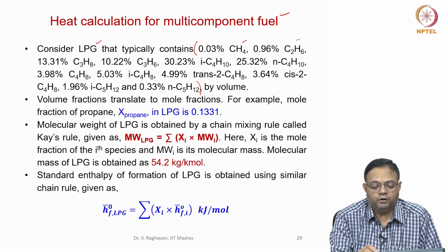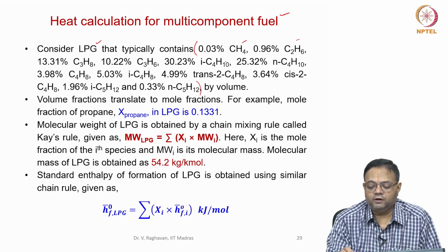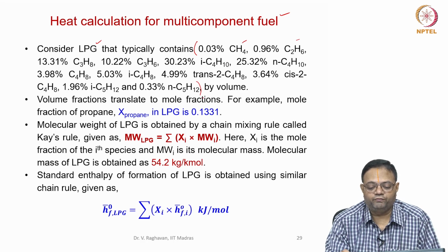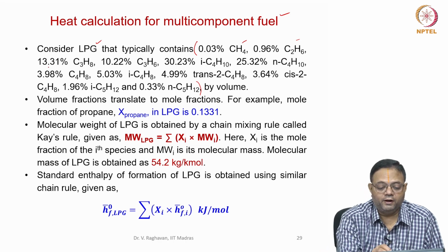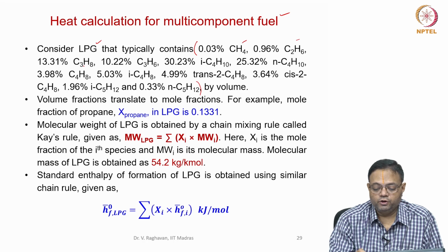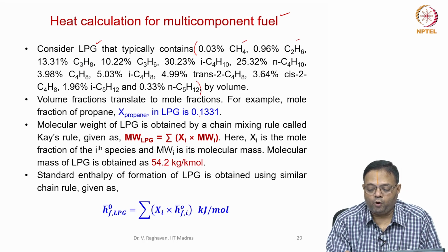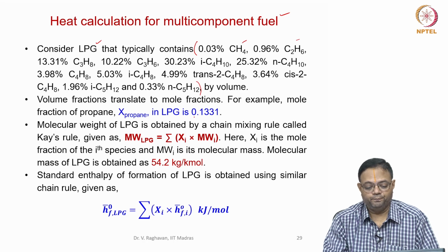Now, the components are specified as volume fractions here, volume percentages. The volume fraction will translate to mole fraction directly. So, if we take the case of propane, propane is 13.31 percent. So, the mole fraction of the propane will be 0.1331.